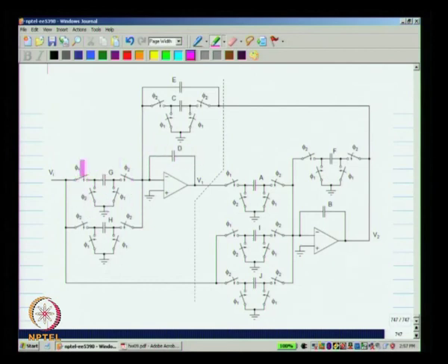So, this forms the delayed integration, and this forms the part for delayless integration. Similarly, I is for delayed and J is for delayless, and this is delayed and that is delayless. And you also see the direct capacitor that is sometimes useful in switched capacitor circuits.